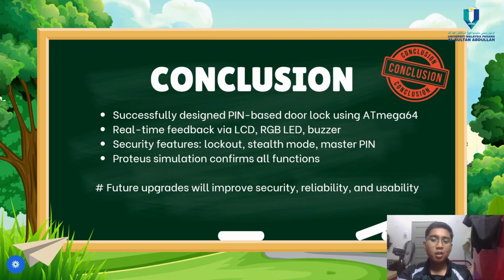So we go to the conclusion. In conclusion, we successfully designed and simulated the pin-based digital door lock system using the ATmega64 microcontroller. The system provides real feedback through the LCD, RGB LED, and buzzer. It also includes important security features like lockout mode after 3 failed attempts, stealth mode for privacy, and a master pin for password reset. Our simulation confirms that all functions work as intended. This project demonstrated the practical application of microcontroller programming and embedded system design for real-world security solutions.